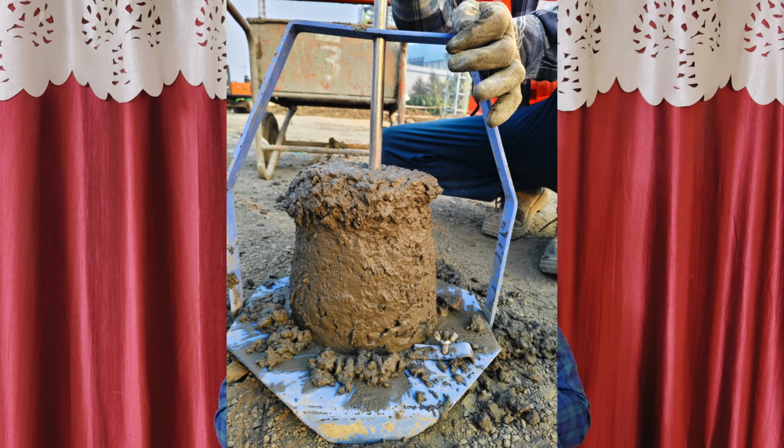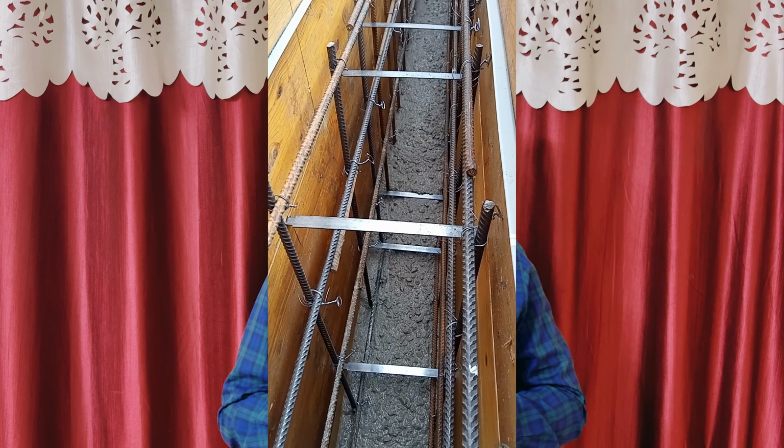So maybe the question blinks in your mind: why does low slump concrete still work with vibration? The myth fixed in our mind is that slump equals workability. That is not true. Slump only measures flow under self-weight, and workability means ease of placing, compacting and finishing. Low slump concrete looks stiff, but it can still be highly workable if vibration is used.